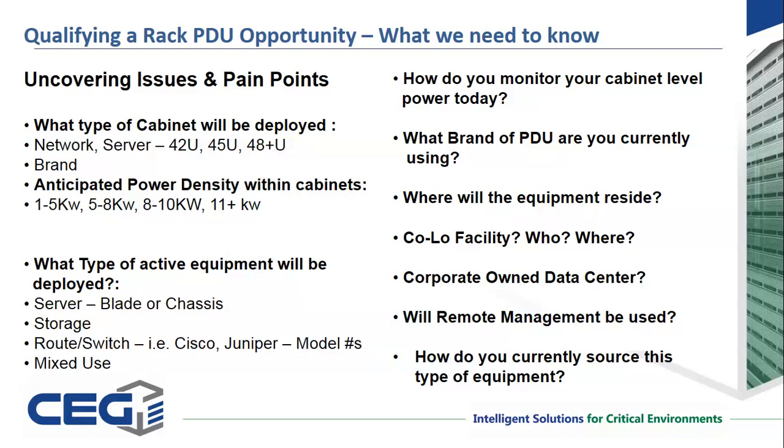Where's the equipment going to reside? Is it inside a data center? Is it in a colo? Is it in an industrial environment? All of these things. Will remote power management be used? If they say yes, we're not quoting just a metered power strip. We're going to have to be at least smart or maybe even switched.